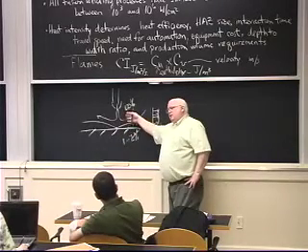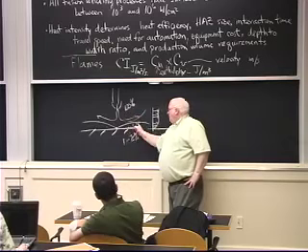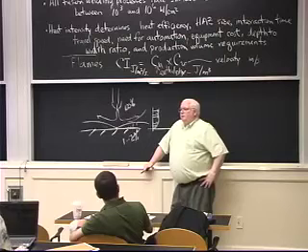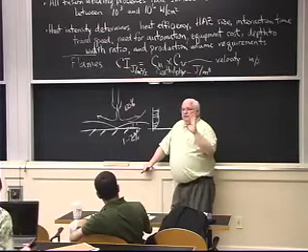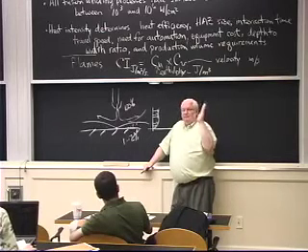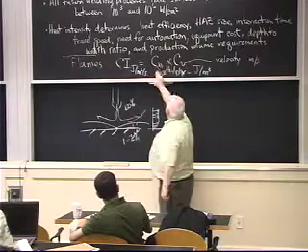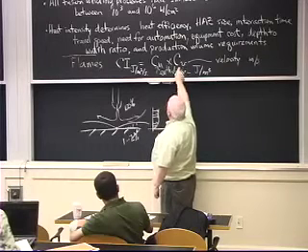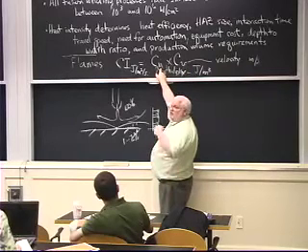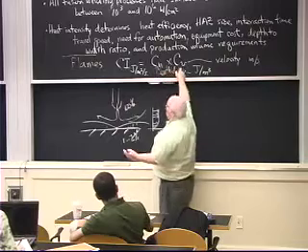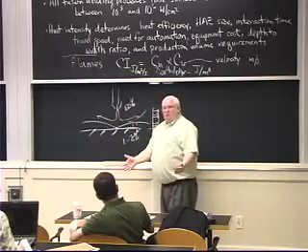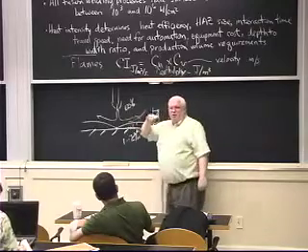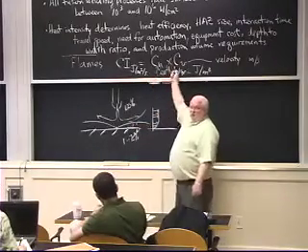If you're now looking at heat transfer from a hot gas to a cold surface, you're going to find that you essentially insulate the surface and you are limited by your boundary layer thickness. And so how do you get a thinner boundary layer? Higher velocity, right? So if I go back up here, velocity turns out to be very important. It turns out the enthalpy is related to the temperature of burning of the gas, and the velocity is also related to the temperature of burning of the gas. There's an expansion of the gas, which gives me the velocity of burning, which is related to temperature. PV is equal to nRT.